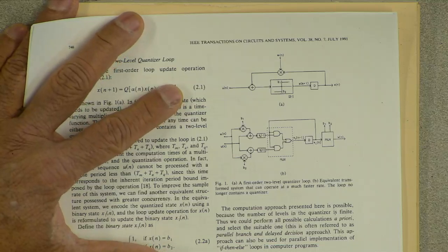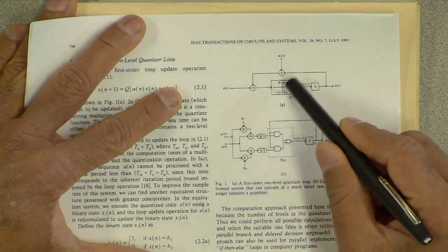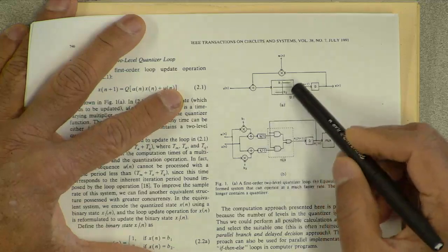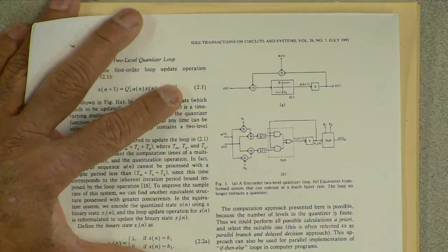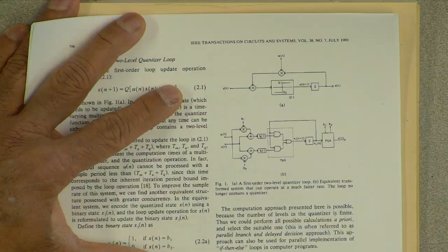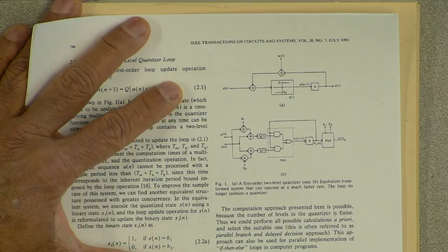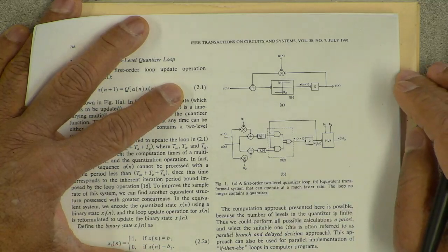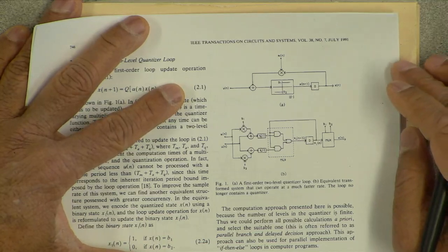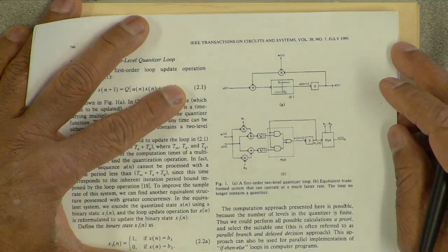We are mapping these to known constellations, and so ultimately these are being quantized to, if it is simple BPSK, binary phase shift keying, which is 1 or -1, or if it is pulse amplitude modulation, PAM4 for example, 4-level pulse amplitude modulation, then they would be mapped to ±1 or ±3. Okay, so there are also schemes that use PAM5, pulse amplitude modulation of 5 levels, particularly used in gigabit Ethernet standards,